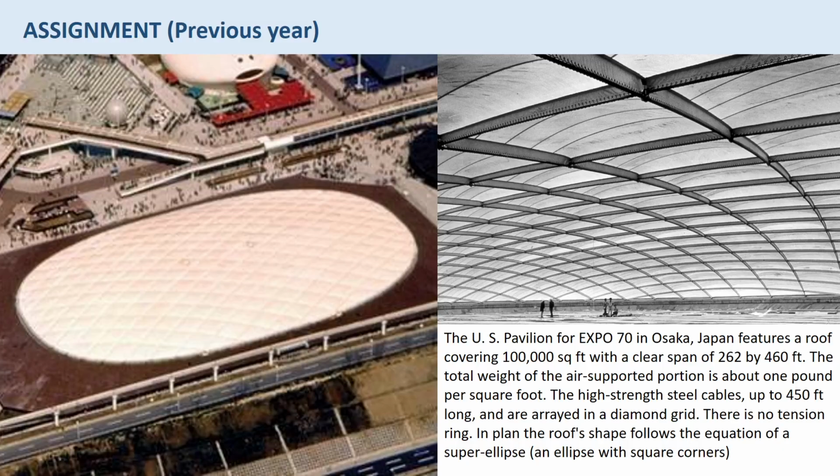A thin curved plate structure shaped to transmit applied forces by compressive, tensile and shear stresses that act in the plane of the surface. They are usually constructed of concrete reinforced with steel mesh and it functions both as structure and covering. Zaha Hadid is one of the architects who uses shell structures in her designs. Very dynamic shapes she uses in her design and she uses a lot of shell structures and curvatures.